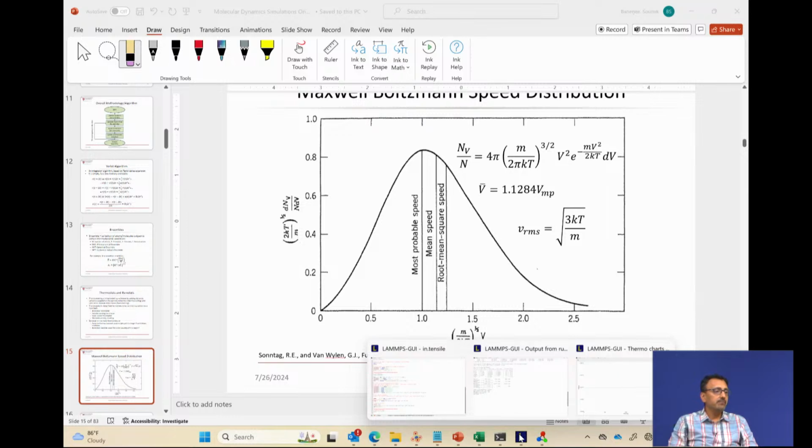It should not be. There are recommendations from LAMMPS. For example, LAMMPS recommends for equilibration that the thermostat relaxation time should be every 1,000 steps, and for the production run, 10,000 steps. So that's what you start with. Now if you have a tricky system, a very structurally messy system, which is not working, then for equilibration you start with a much stronger thermostat and a low time step, right?